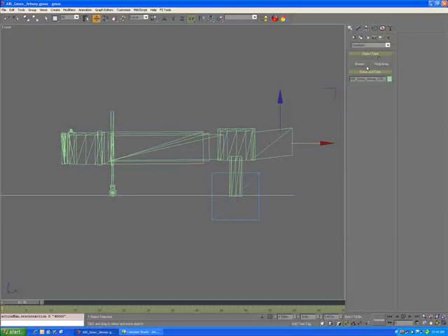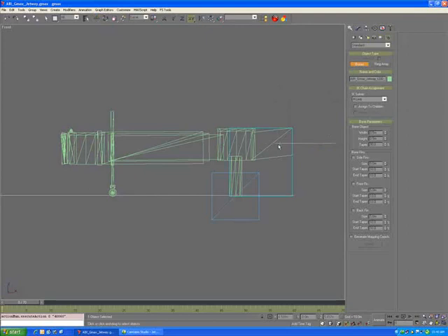So I've already aligned that, so that when I draw the bones, the bones themselves will align to the pivots. So I'm going to select bones, and I'm going to choose the side view. The side view seems to work the best. Bones have standard orientation anyways, but the side view seems to be the best for drawing them. As you see, as you hover over it, it will lock to the pivot. So I'll start with the root node back here, go to this next node here, and then the next one, and to the next one, and not the leg, but to the final one out there.